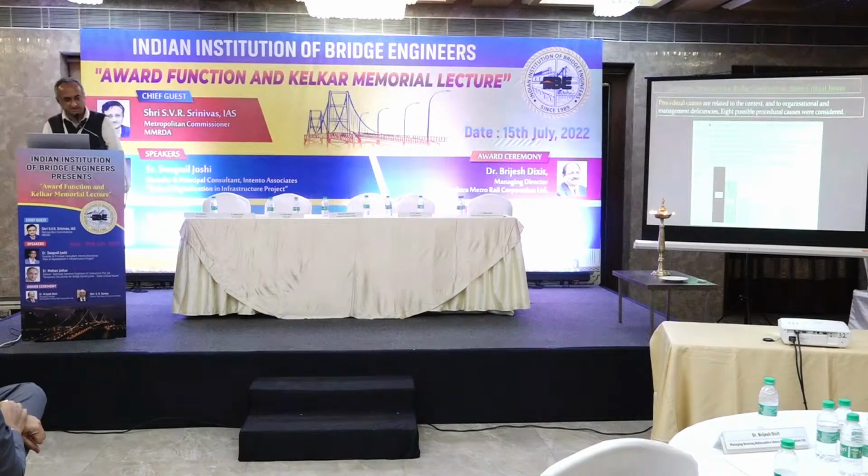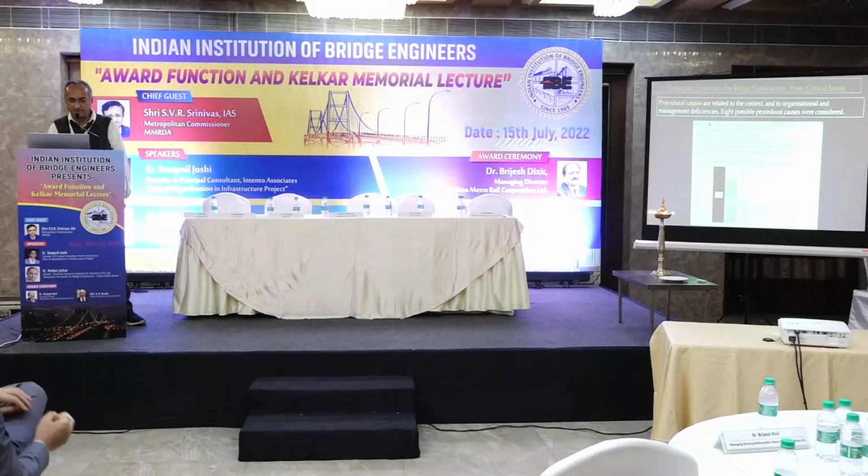Procedural causes are related to the context and to the organizational and management deficiencies. So 8 possible causes they have analyzed. And the most predominant one was the inadequate review of the false work design, assembly and operation methods. Again, overall means other unknown causes, again 44% of the cases.